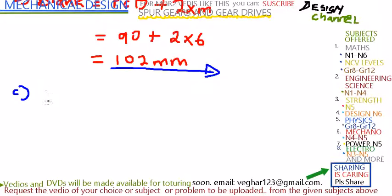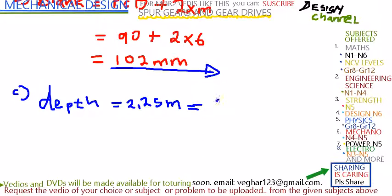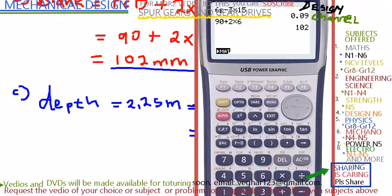The depth of cut, you just say depth, which is equal to 2.25, not millimeter, it's the module, so it's 2.25 multiplied by 6, which is the module. So when you're calculating this one, you'll have something like this.